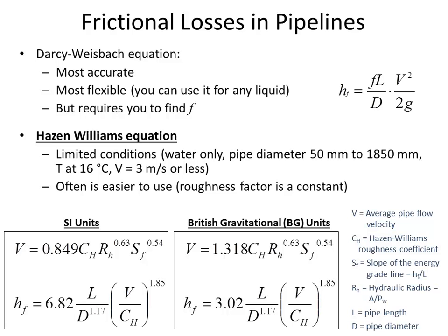And remember, S sub F is H sub F divided by length. And so elevating the tank is going to marginally increase the pipeline length, but what it's really going to increase is the H sub F, because you're going to have some additional elevation that's the driving force. And so the velocity will increase in response to that. It will come back into a new equilibrium when you raise the tank.